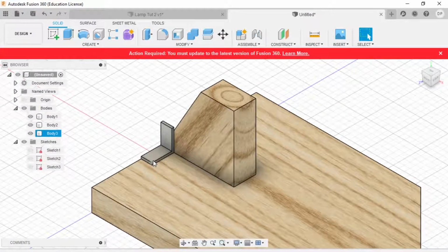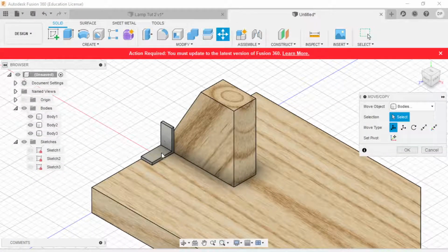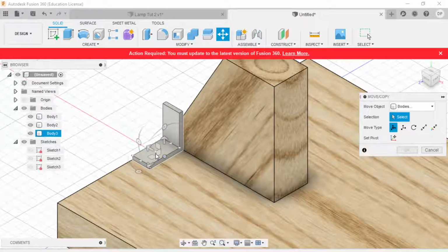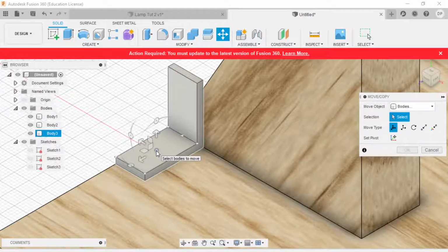Now we have to do a depth here, so we're going to manually move this part over. Similar to our align, as we hover our mouse over the object, it has all different areas that it's trying to attach to. That's just to do your frame of reference. When it comes to the Cartesian coordinates, x, y, z, it doesn't really matter. But where it does matter is when you start to do rotation, because where you put your mouse, the point you pick as the center of rotation is going to change.